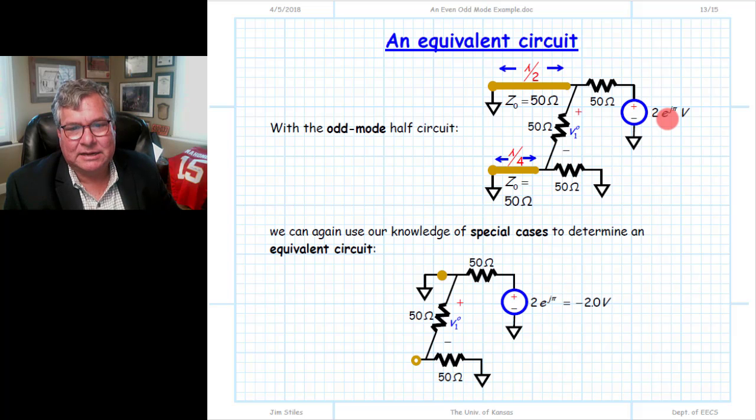So we go through and analyze this, and once again we have these transmission line structures. Both of these are terminated transmission lines. We want to replace them with their equivalent circuit. Again, this one is lambda over 2, and we've just talked about this. The input impedance for this structure will be simply equal to its load impedance if it has this length of lambda over 2. Well, the end of the transmission line is connected to the ground plane, the bottom conductor. In other words, the load impedance is 0. It's a short circuit, and therefore the input impedance is 0.